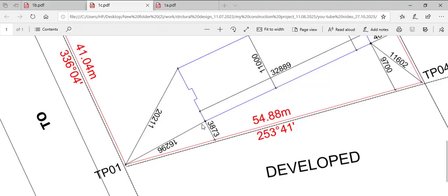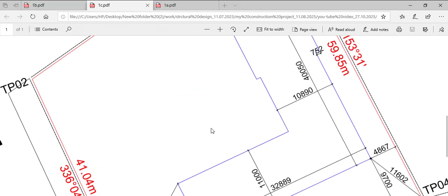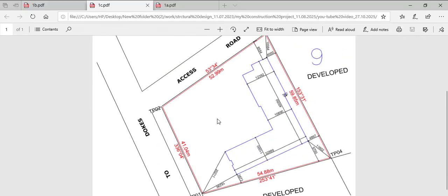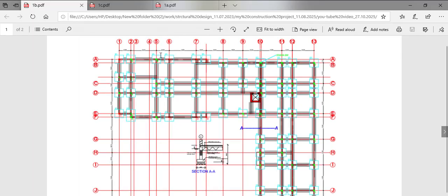What the surveyor does is to create the edges of your building in line with the points on ground, so that your work is perfectly aligned and arranged. So when you do that, you need to now check the footings depending on what type of foundation you will be doing.